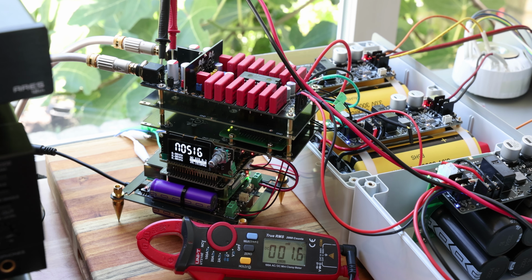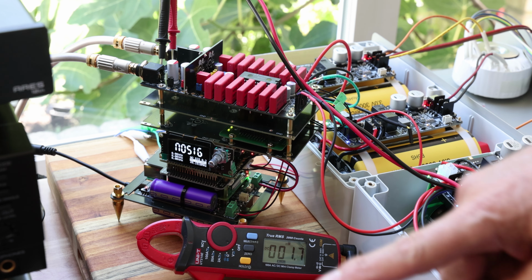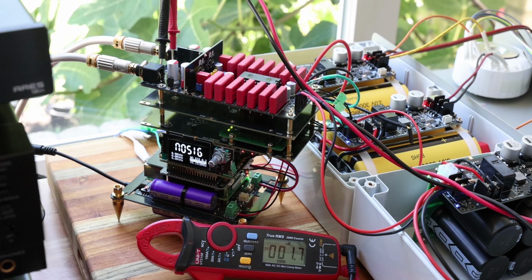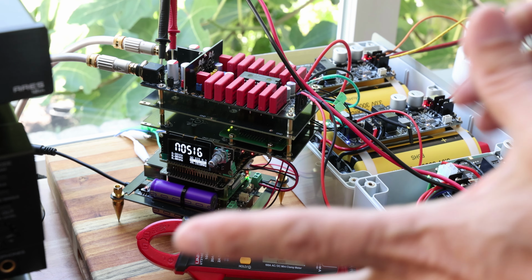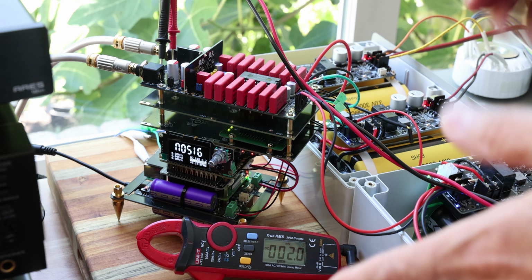The good thing is the maximum voltage you should get out of here is 2.3 volts. So you're still within the tolerance of most amplifiers in that 2 volts up and down gyration. But once you start playing music, you definitely want that to be as close to 0 as possible. Somewhere in the 200-300 millivolts, you'll be fine.